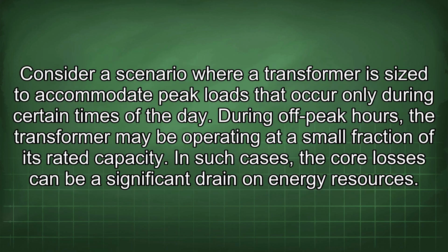Consider a scenario where a transformer is sized to accommodate peak loads that occur only during certain times of the day. During off-peak hours, the transformer may be operating at a small fraction of its rated capacity. In such cases, the core losses can be a significant drain on energy resources.